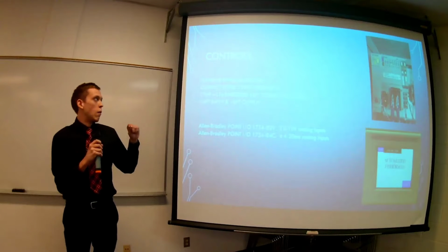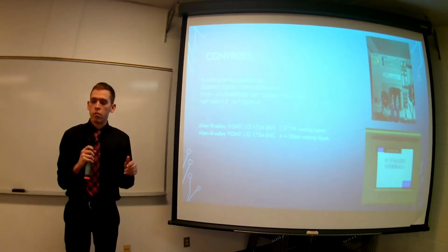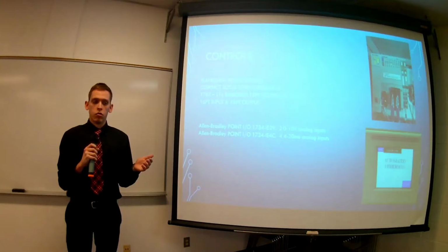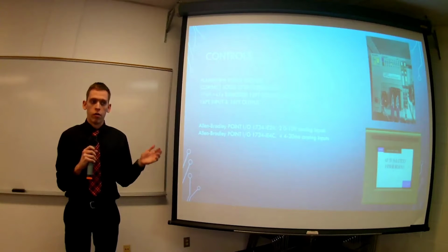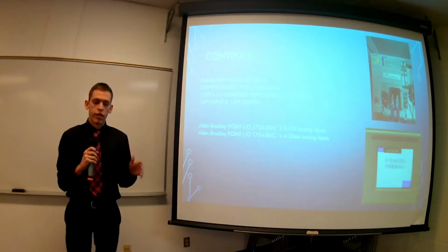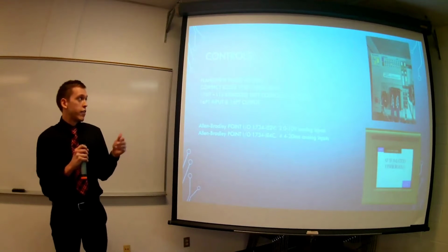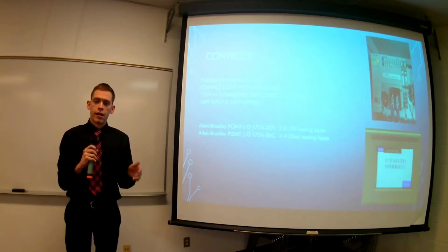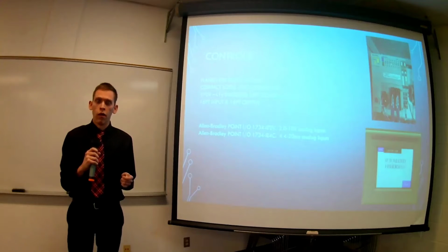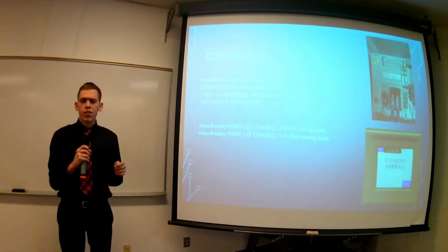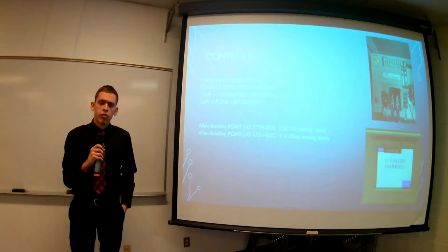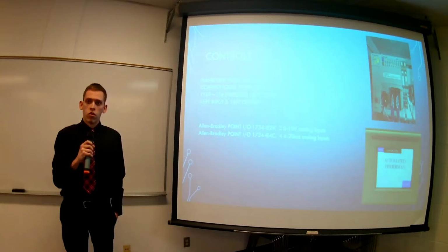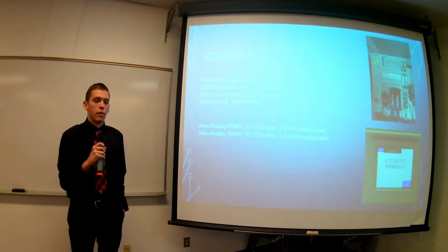So what we're using for our HMI is a PanelView Plus 6600 HMI. That's what we're using to run through the entire program to be able to set your fishing depth, be able to control when you want to reel in, reel out, all your fishing condition sensors as well, everything you can see using that HMI. Along with that, we are using a CompactLogix 1769-L18 controller, which also has embedded I/O, 16 input and output points as well. Along with that, we have two expansion I/O modules as well. We got a 1734-IE2V and a 1734-IE4C. One of those is our 0 to 10 volt analog input, and the other is our 4 to 20 milliamp analog input.